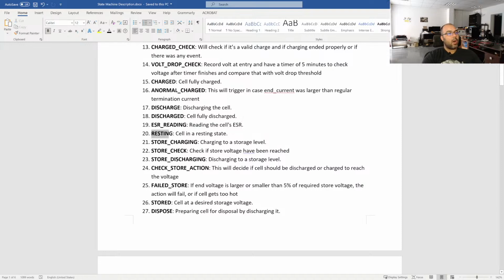I'm not sure how close I will get until I start working on that, but I will do my best to get it as close as possible. We'll be using the volt drop method, so we'll apply a current, but in the new version I will be able to set the current to 1 amp, and that should make the calculation better.